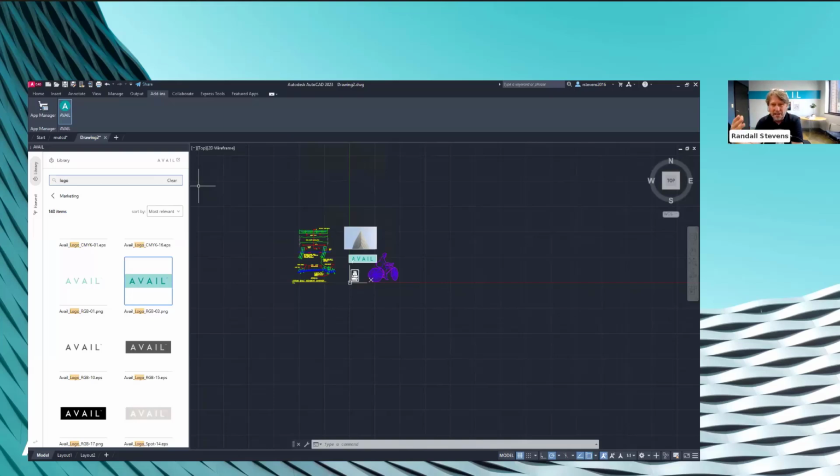So you can think about a material that you might have in Revit. That material, if it's got textures, that's an external file that needs to be in a certain location in order for Revit to know to see it, to render. So that's what we would refer to as routing. So more and more, we're thinking about how not only are you centralizing these resources, but can we route that data and put it where it needs to be on each user's machine in order for this stuff to work?